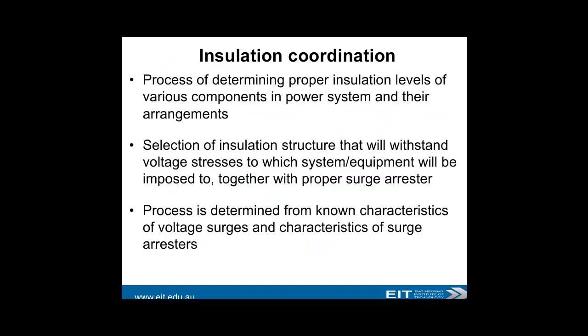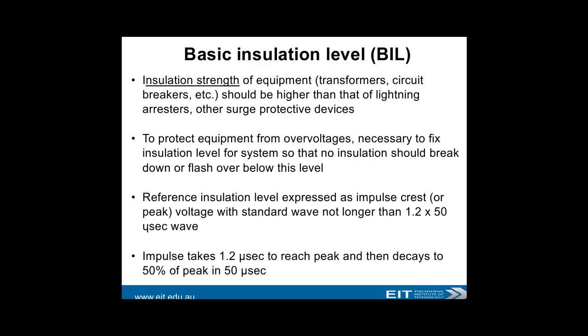We'll talk about the pulse later. Insulation coordination is very important. Basic insulation level, reference insulation level, is referred to as an impulse crest with a standard wave not longer than 1.2 microseconds to reach the peak and 50 microseconds to decay to 50% of the peak. This is quite an important definition.